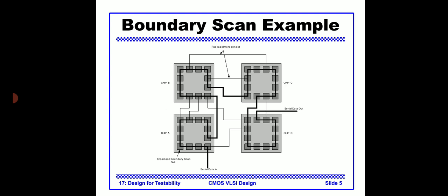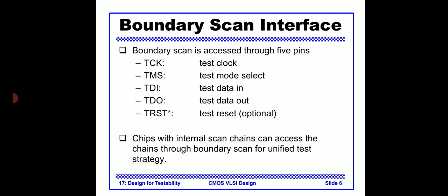Looking at the chip infrastructure, this provides the boundary scan capability. These cells are connected together to form the external boundary scan shift register, combined with control circuitry. These pins allow the integrated components to be tested as if they were separate chips, and they are used for several internal scan issues.